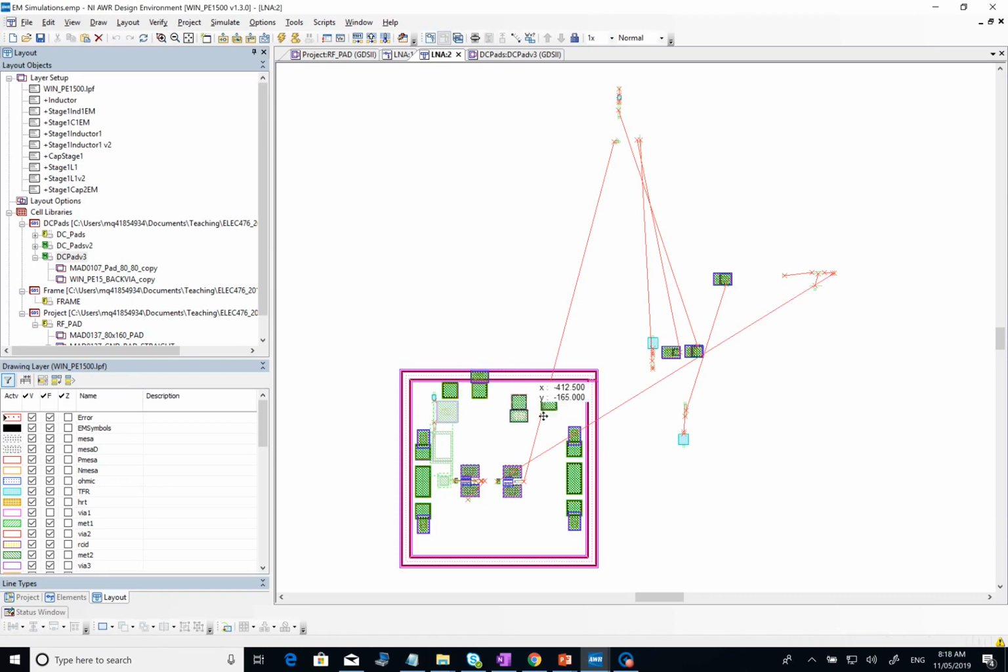And then another DC pad, let's say this is for the drains, and then you need to have one for gates and signal ground. So these pads will supply, say, drains, and these ones for gates. So you need to have 4 DC pads if you have a 2-stage, right?